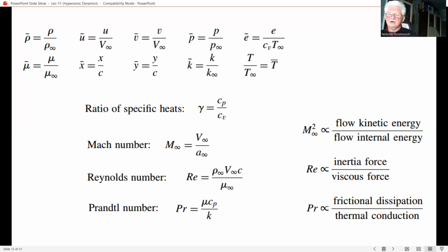For a chemically reacting gas, Prandtl is also dependent on the local chemical composition, which in turn depends on the local temperature and pressure for an equilibrium flow, and on the history of the upstream conditions for a non-equilibrium flow.